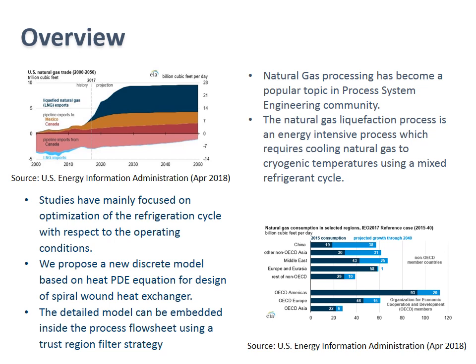In this study, we propose a new discrete model based on fundamental heat equation for design of the multi-stream heat exchanger. Along with this, we also propose a trust region strategy which can embed the detailed design inside the process flowsheet model.